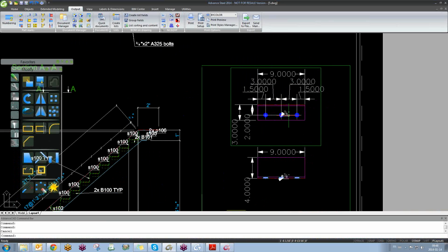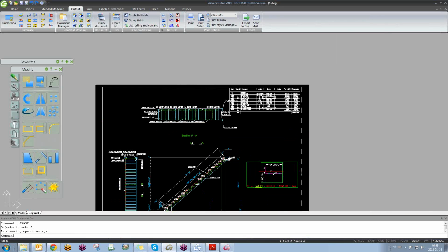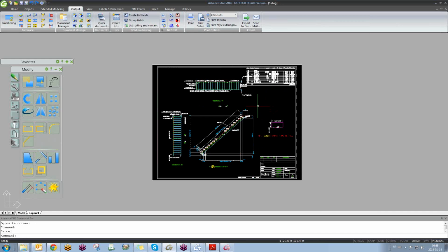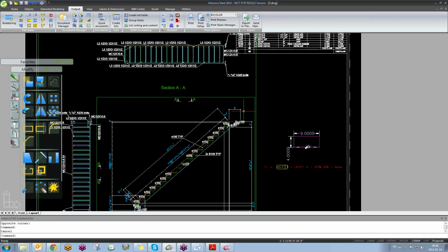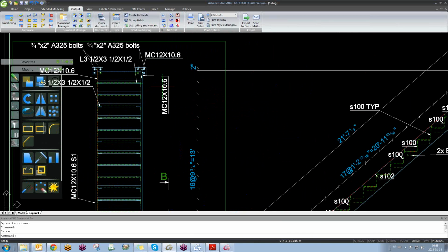Because what I would do, I'll create all my views and everything that I wanted from this one main drawing here. I know it'll be junky, it may not fit on everything, but then I'll make a copy of this, number 5, and say 5-1 or whatever, and then explode 5-1. Then take off what you don't want, and then you still have this main one that'll be tied back to the model. Yeah, and if you forget something, you could just copy it again. Copy it again, exactly.